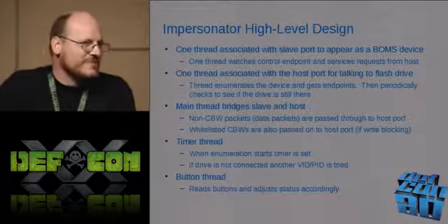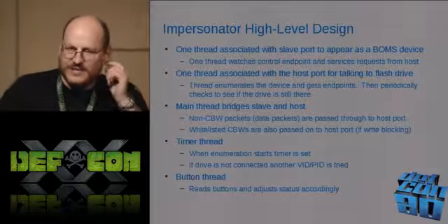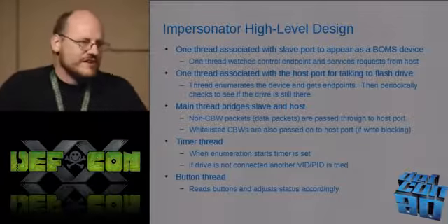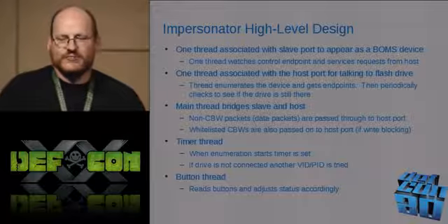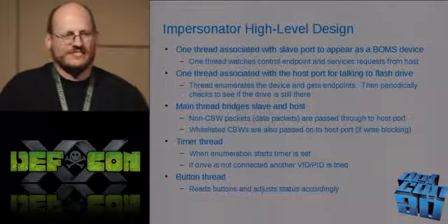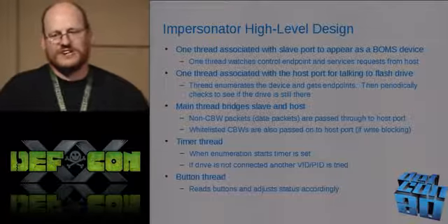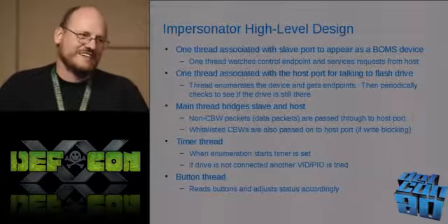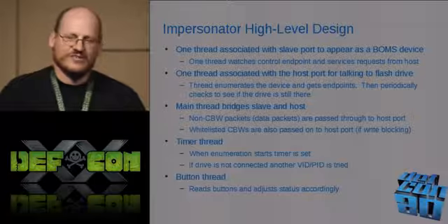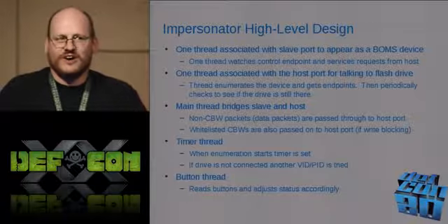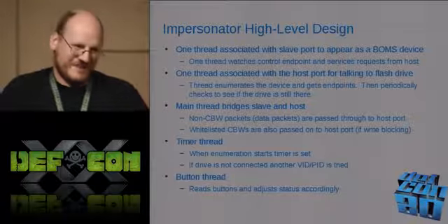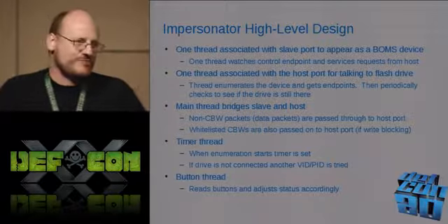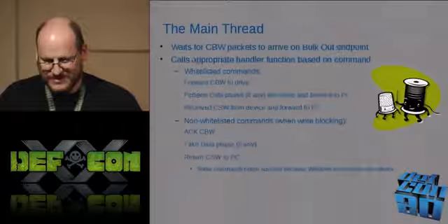Also, there's a timer thread, and what the timer thread does is, if you're in automatic mode, whenever the PC asks for a device descriptor, it says, oh, someone's trying to talk to me, and it starts a timer. If they stop talking to you after a second and they don't ask for additional descriptors, it says, oh, someone's blocking me. I'll go to the next one. And that's how that works. And there's also a thread for reading the buttons that come in.